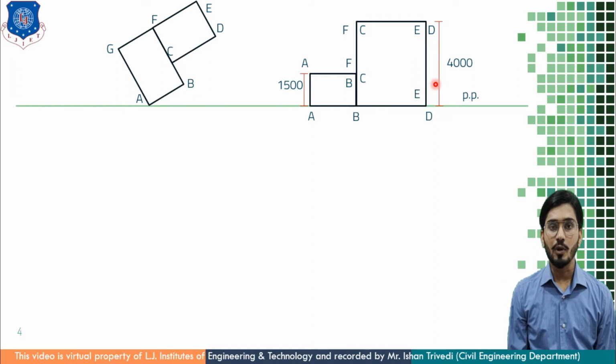And then I will plot a perpendicular line to the picture plane and mark the U1 point. So this actual phenomenon is now being applied in 2-point perspective. At 12,000 mm, I'll mark a point SP. In your sketchbook, as the scale is 1/100, you have to mark this point at 12 centimeters.